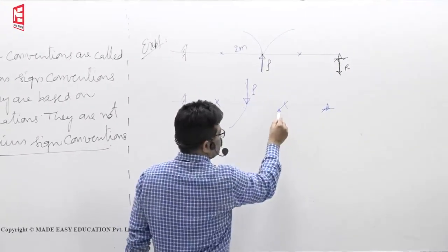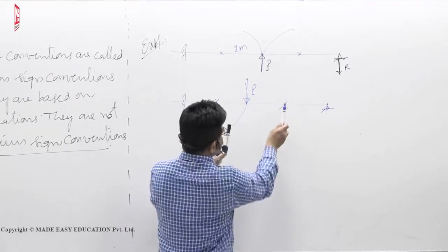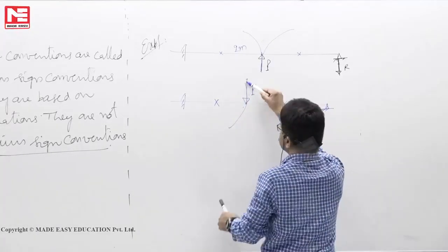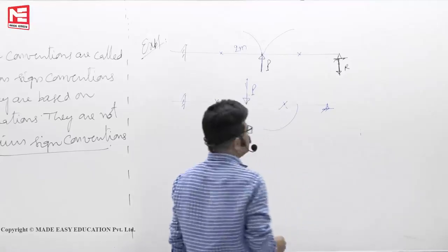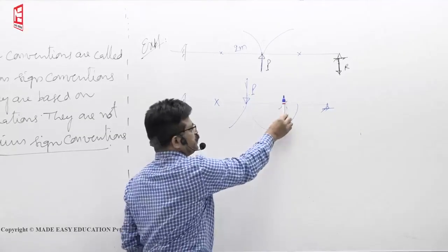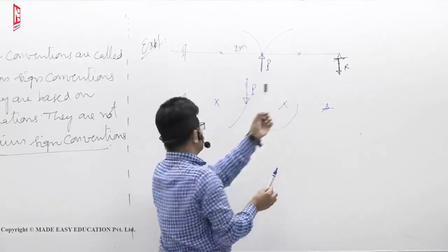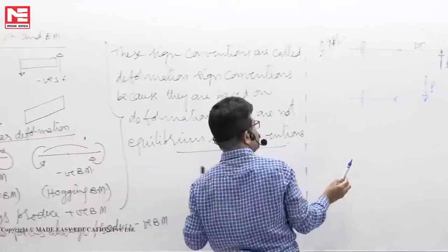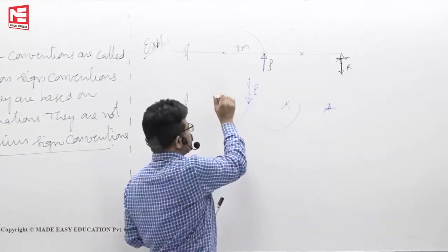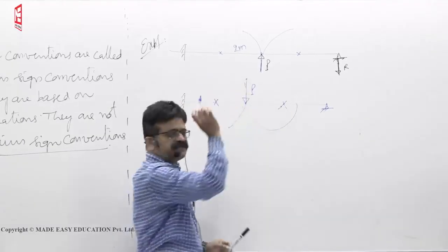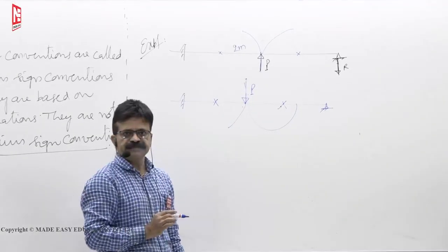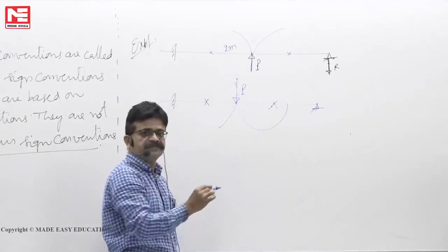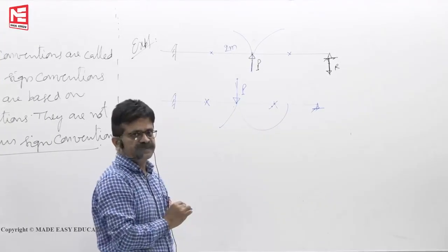I want to find bending moment here, say. Stand there, look at this force. Tail to the head towards the point. Like this. Anti-clockwise. So section left side anti-clockwise. Section left side anti-clockwise. Negative bending moment. So whether I stand here or here, this will always give negative bending moment. So first task is you have to stand here, then find the bending moment.